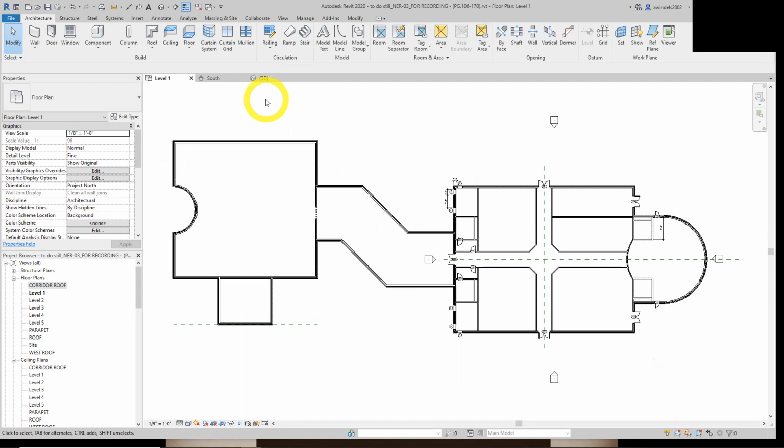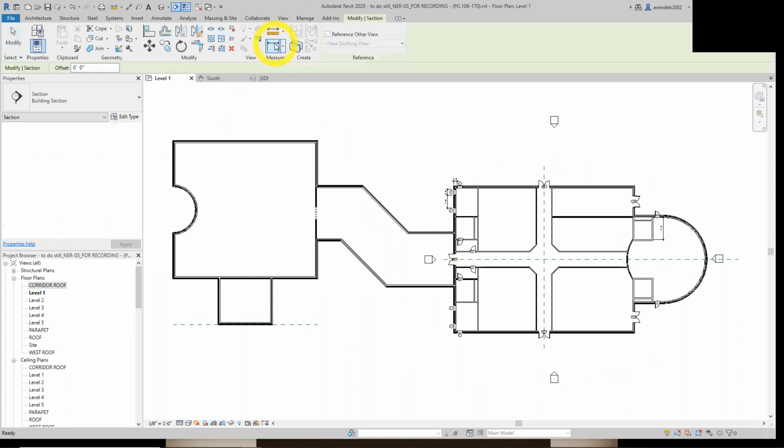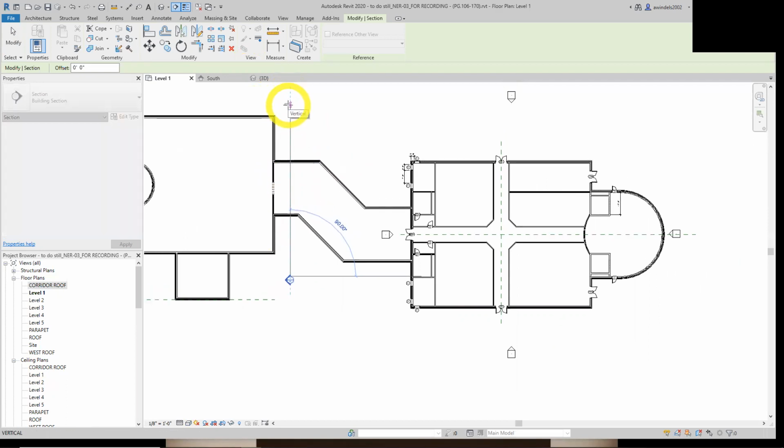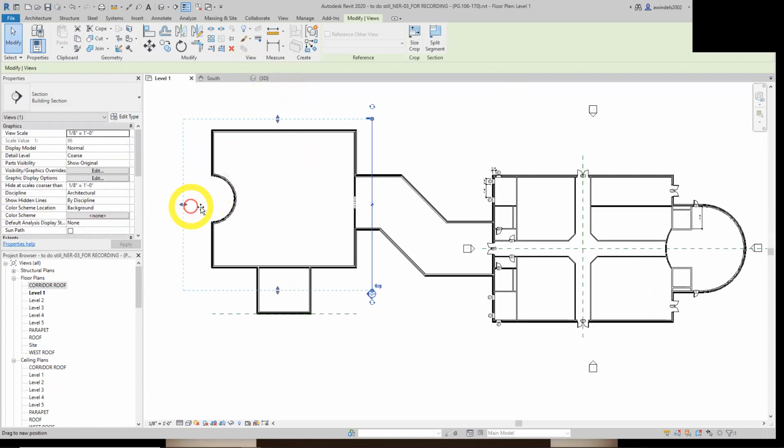So we're going to go to create panel, view tab, and sections. So we're going to do our first building section. We're going to do it similar to the head and the tail of it, similar spots to the picture on page 127. Vertical direction, keep it vertical, no angle. Well, 90 degrees, but vertical. Accept that. That's the space of our section. You can edit that later.